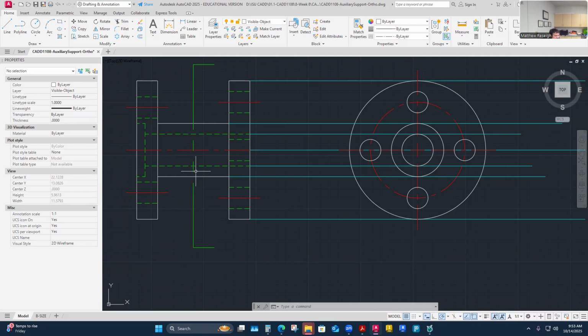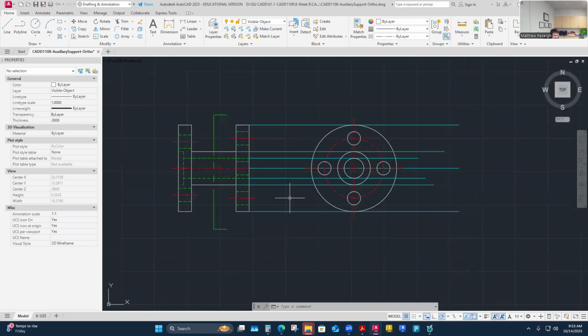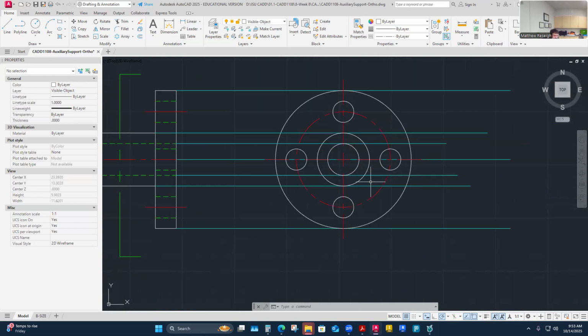I view this as more of a pipe feature that has an inner bore and an outer bore, ID and OD, and then the space in between those, where the material actually is, we'd call that the wall thickness. Rectangular parts have that, square parts, they have a thickness materials do associated with them, and we might call that wall thickness, how thick it is. And so I'm going to add that sectioning, hatching through this area here.